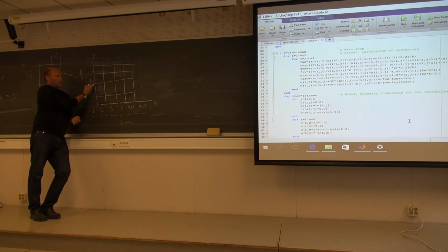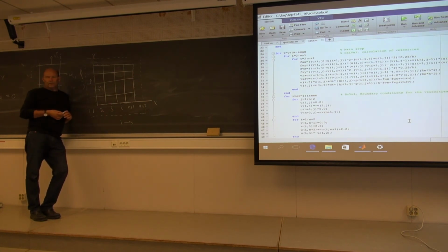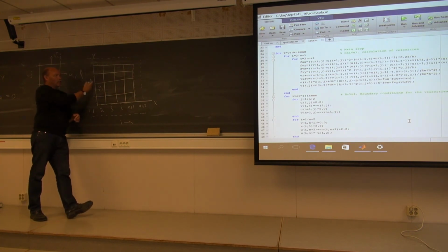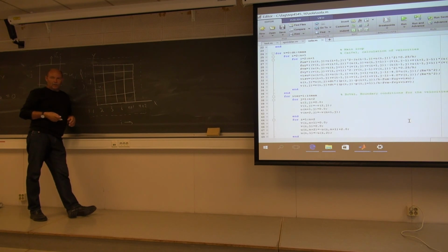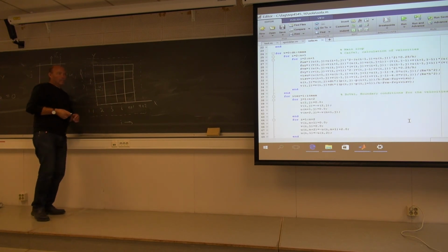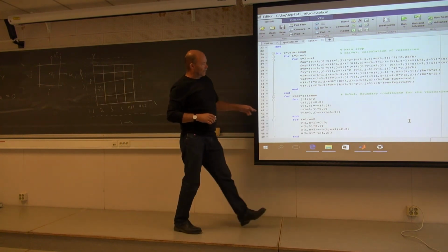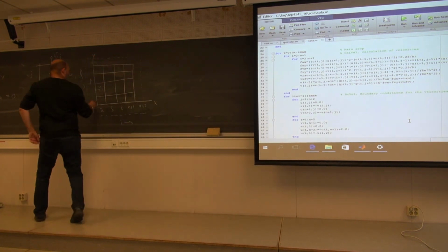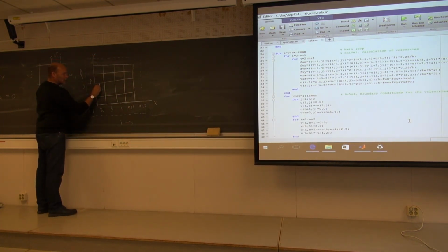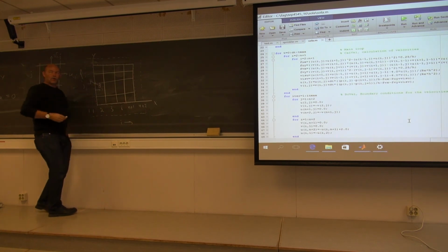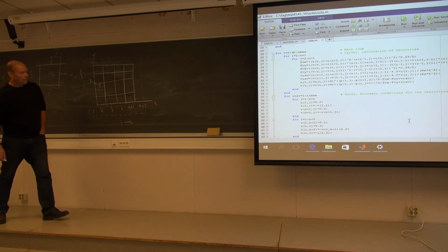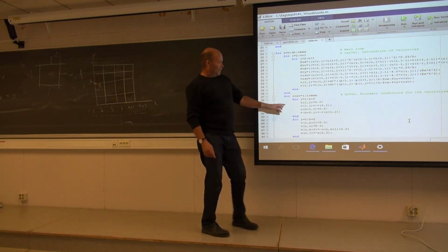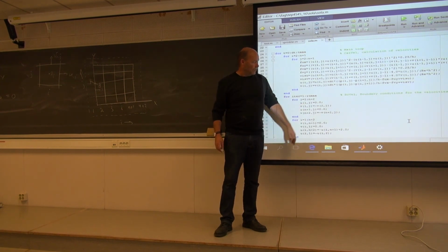That's not good. I want it to be 0 on the wall. I mean, we have the no slip condition, so no velocity along the wall. But what about half a cell inside the wall? Makes no sense. But we now do the trick, as you can see here. It equals minus v number 2. So that's the trick. If you have a velocity here inside your domain that goes down, then we create another one here, positive, so that you find 0 in between. That's the whole trick. So v number 1 equals minus v number 2.